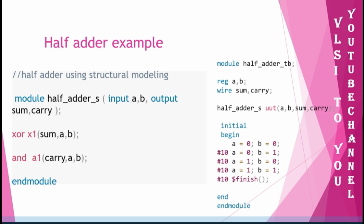You can analyze how you could pass the values, and if you want to check the output, you need to give some $display or $monitor here. After $finish, or you can take another initial block and give $monitor or $display in order to see what is happening, in order to get the output displayed on the screen. Why is it?